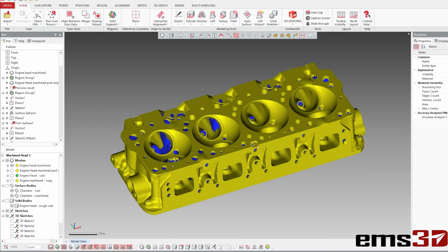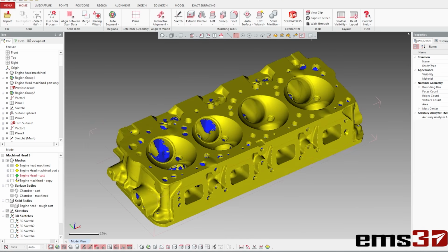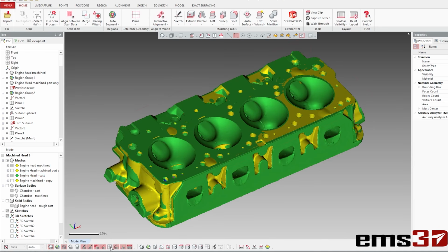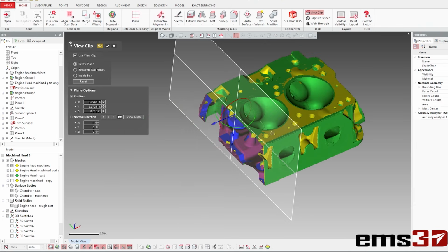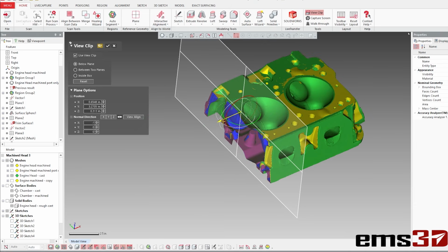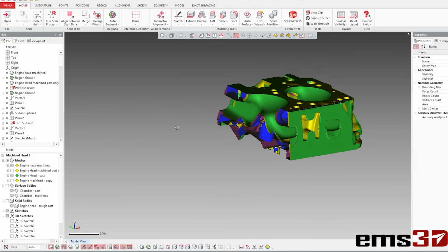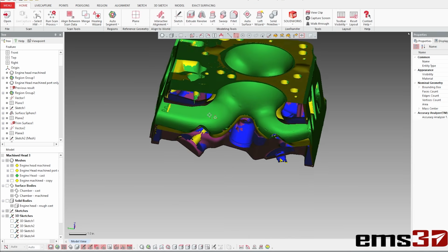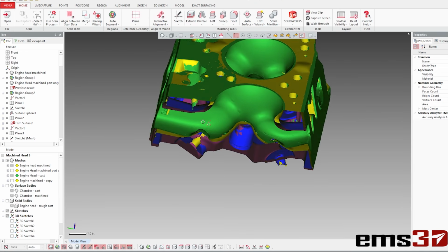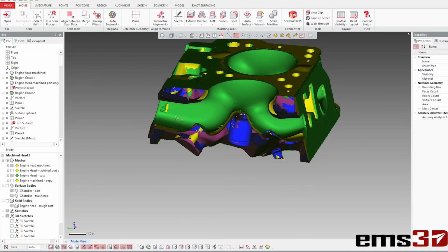And so now I want to show you a comparison of the difference between the two. So let's start with turning on both scans, and I'm going to come in here and do a view clip, and we'll flip this to the XY and flip it around. And if we slide over this, kind of put it right there in the middle. I'll hit stop. You're going to see, and I'll show you the surface model as well, but here's the rough casting, okay? So in green is the rough casting, and you can even see some of the stuff in there from the original casting.